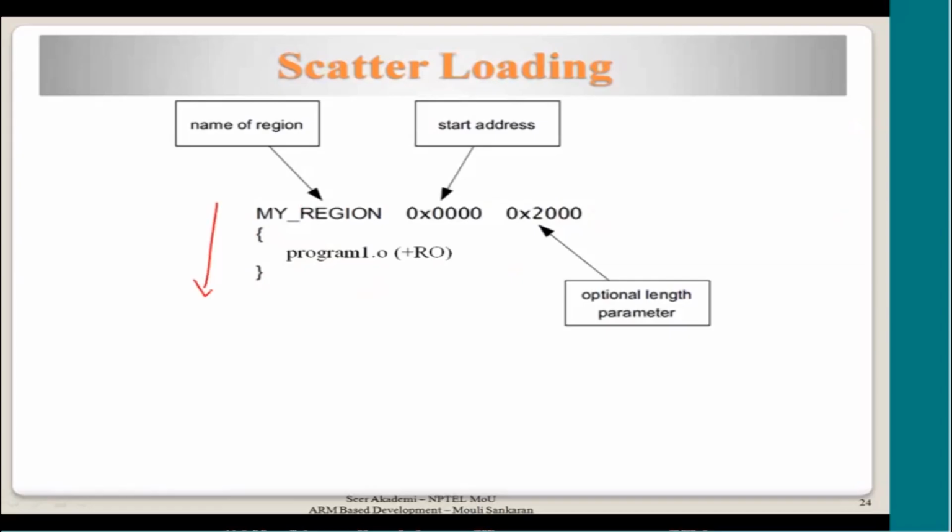You should be aware of this so that when you are developing software for a particular hardware solution, you will be able to position the code wherever you want. Suppose you want to keep the ISR routine in the lower address range, whatever it is. Then you say all the ISR routines are written in this particular function, in this file, and that this particular OBJ file needs to be placed here. Then all the ISR routines will be residing in that particular memory.